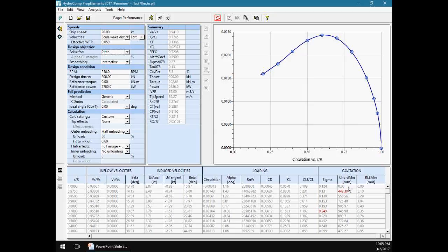So you have a variation in angle of attack that looks at these, and the chord length representation that we have here really is not based on the traditional cavitation criteria that you might consider for a system level, like 5% cavitation or sigma tau charts and some of those things, or blade pressures, because that's a whole propeller blade metric. What we're trying to do here is to provide a cavitation criteria on a radius by radius level, and that's why we use that kind of a specific criteria as opposed to a generalized criteria.